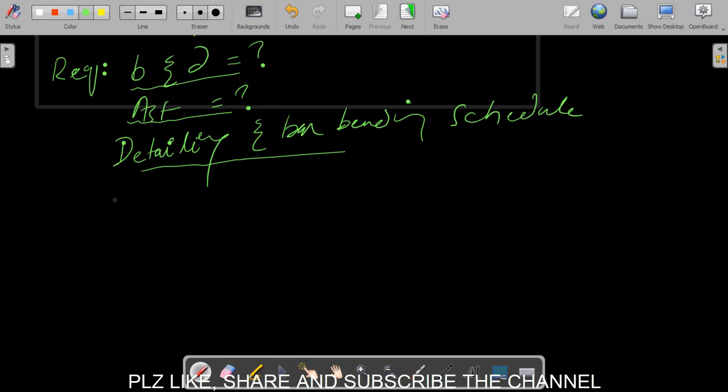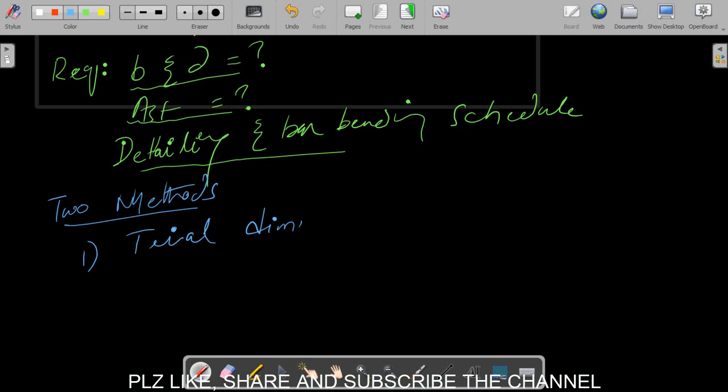Any beam can be designed by two methods. The one method is selecting the trial dimensions of the beam, right? This method is usually used, trial dimensions. That is, we assume B and D by using some kind of thumb rules.